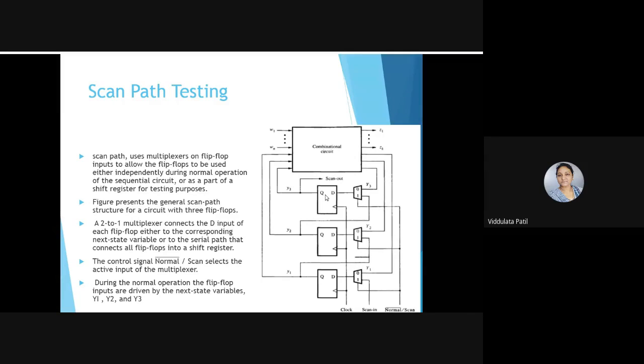Okay, that means only one input is going to change the output, others will be in such a condition that they will not make any difference in the output. Okay, and then we are going to check the output, and that means we are making one path active, and we call that path sensitization. Okay, in technical terms we call that path sensitization.